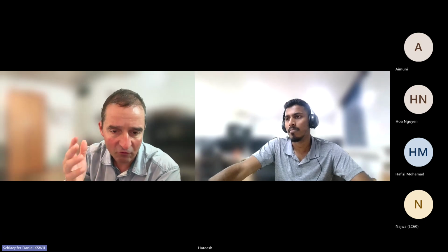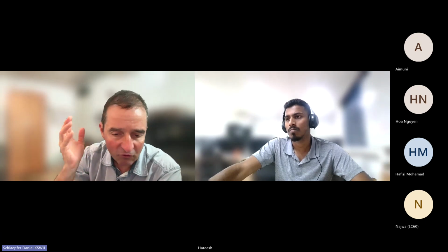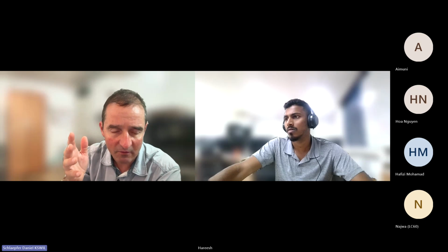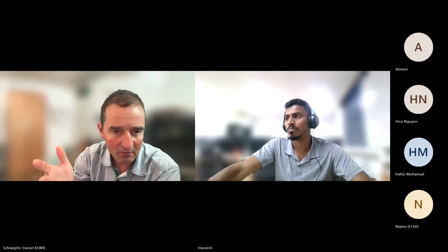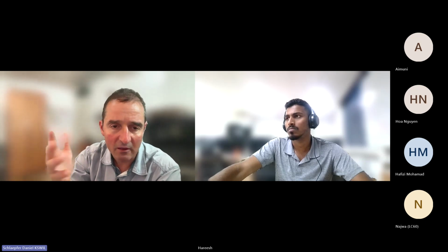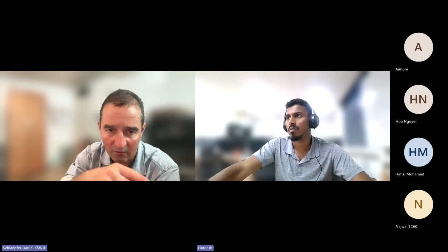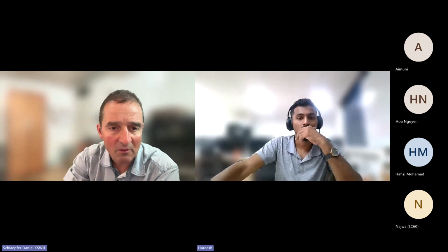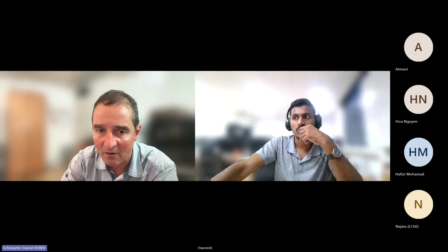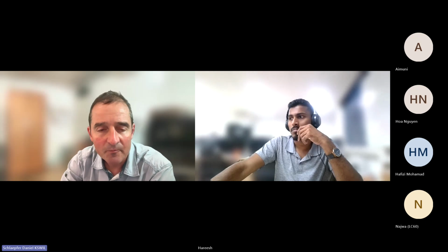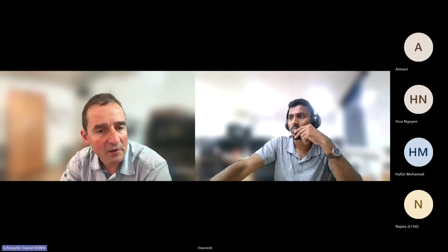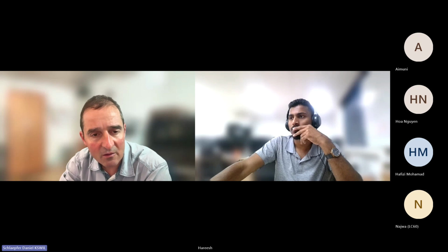The function is usually a ratio between multispectral bands, for instance 2.3 against 1.6 or 1.6 against 1.0 micrometers band in Sentinel. And if you have this function, you apply it to the image. You do the same ratio in the image, and that's it.